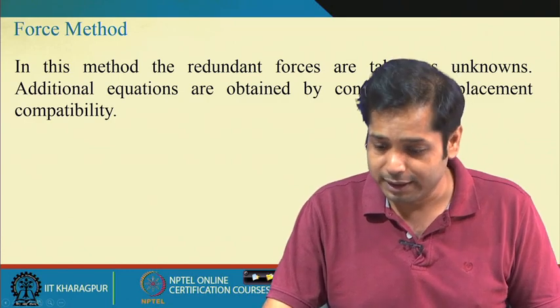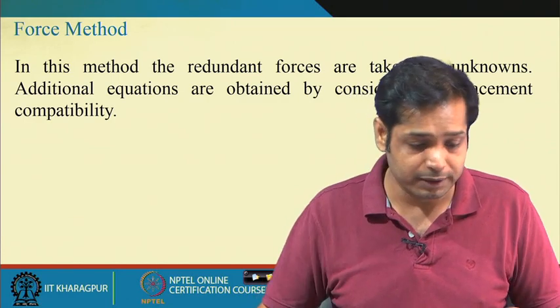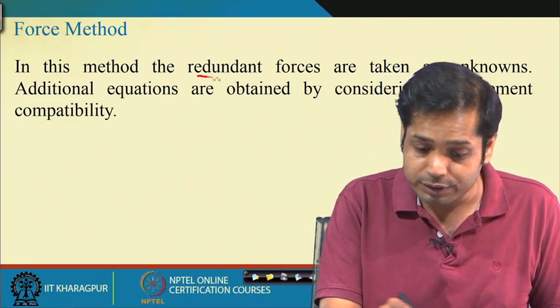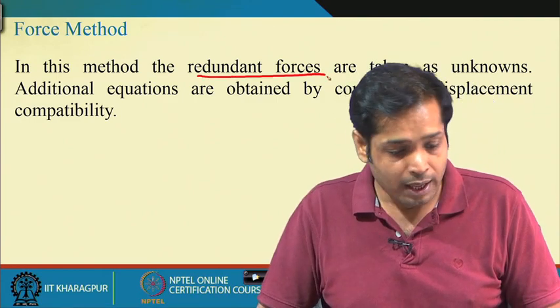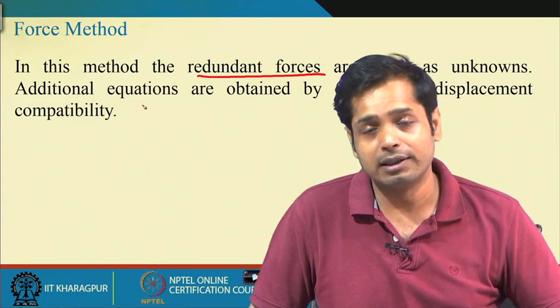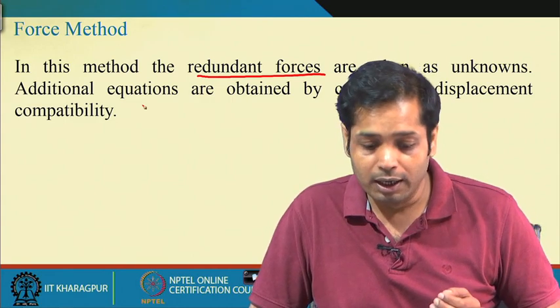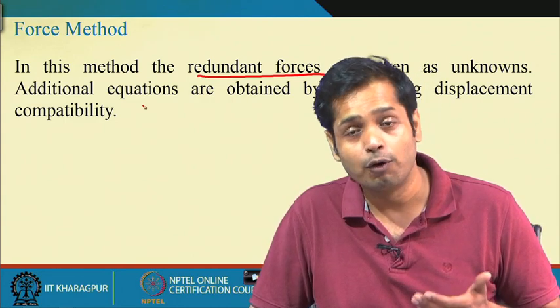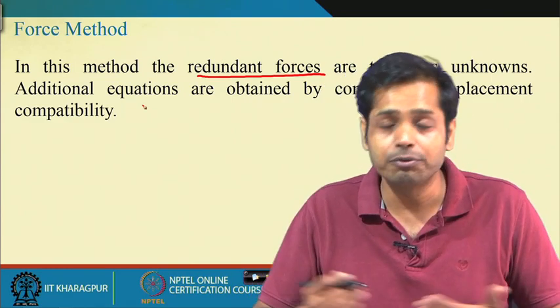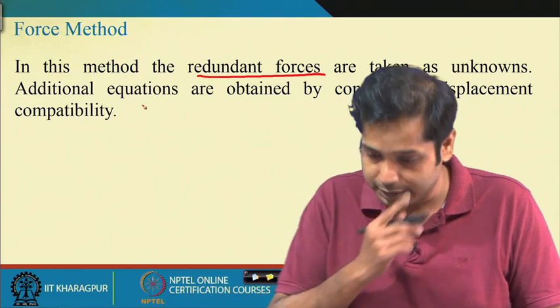Let us first define the force-based method. In the force-based method we take the redundant forces, the unknown forces, and the additional equations are obtained for the statically indeterminate structure or any indeterminate structure. It means that there are some unknowns for which we do not have equations, and we have to formulate those equations, and based on how those equations are formed we have different methods.